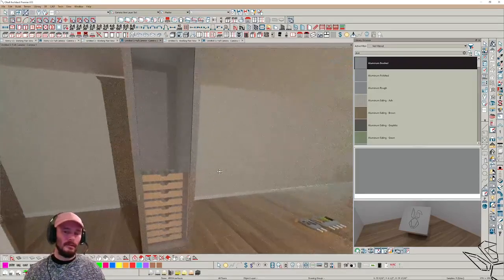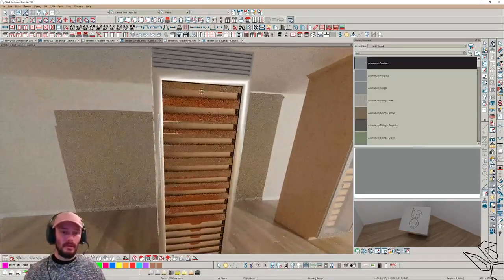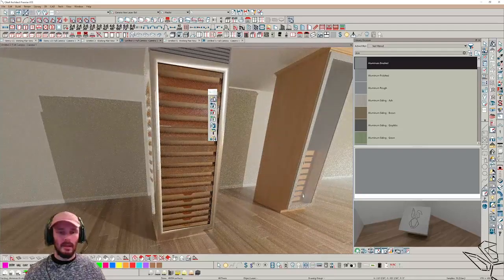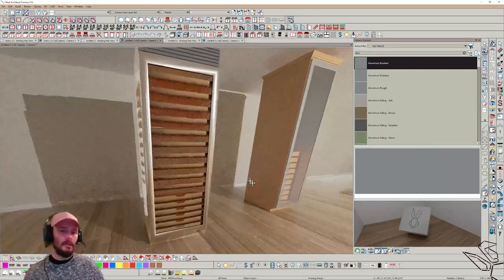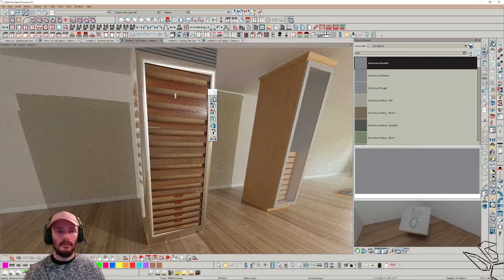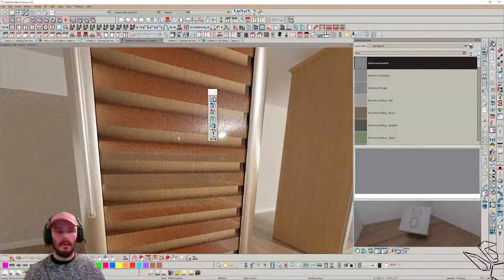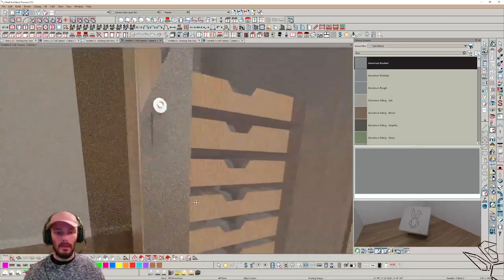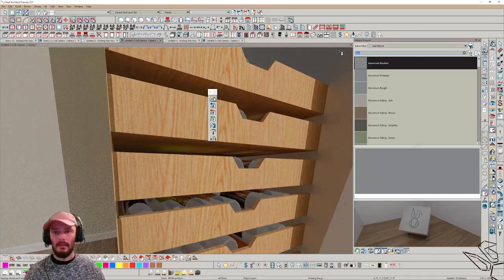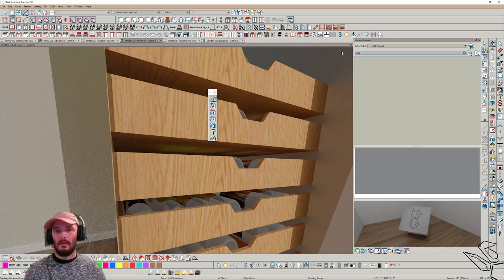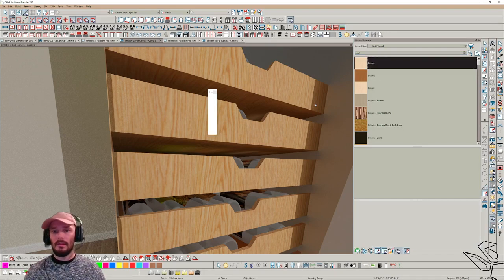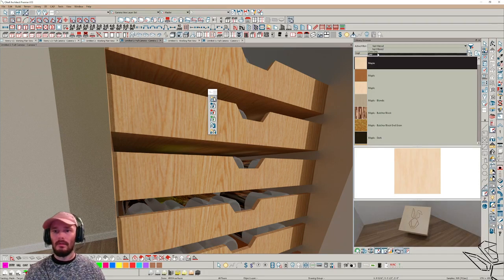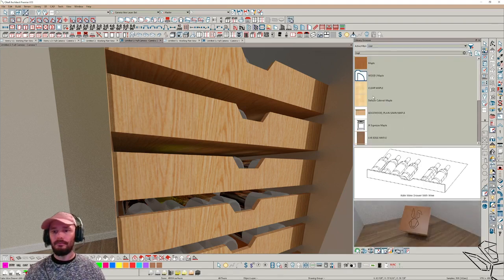So, same process, by the way, for these upper trays. You can steal these upper trays. Also, once you steal them, you can change the orientation, you can see here, we've got an issue with the grain going the wrong way, or improve on it, use a different texture. I know that I have some good wood textures, like if I go to my user only catalog, got some good maple textures, we've got good live edge textures.